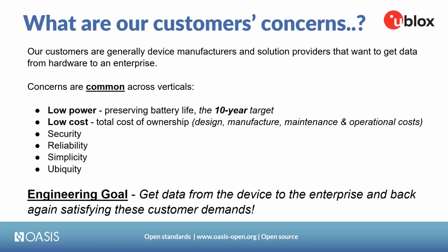So massively oversimplified, the problem's simple enough. Power usage on these devices is a function of time on processor and the time the radio stack is up. And operational costs are a function of the number of bytes sent across the network. So coming up with a solution which limits both of these things was the challenge. We needed to find a protocol and networking stack that allowed us to do this.